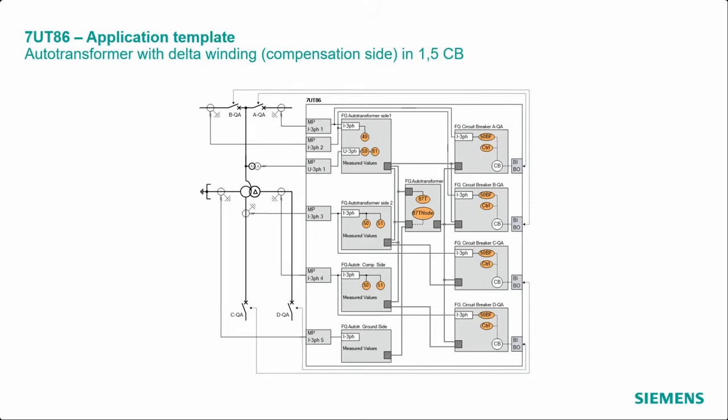And for that special case where we have 2 times the differential protection, please have a look here at the function group in the middle, function group auto transformer. This function group now contains 2 times differential protection. That means you can instantiate here 2 times the differential protection in that project, and then you can make the selection in the settings if it is a normal power transformer differential, or is it a node point differential protection. And for that application, you see it as well here.